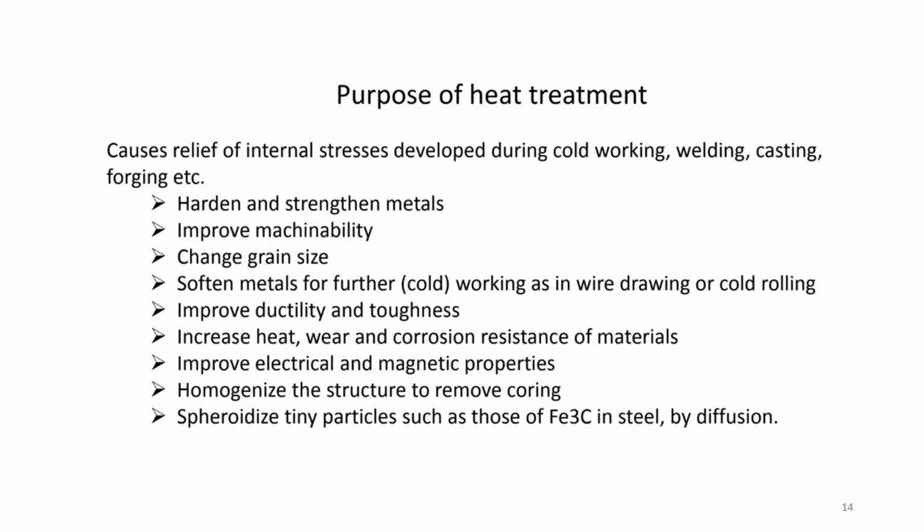These are various purposes for the heat treatment. So heat treatment causes relief of internal stresses developed during cold working, welding, casting, forging, etc. It also can harden and strengthen metals, it can improve machinability, it can change the grain size. For example, in normalizing, you get the grain size which is lesser than initial grain size.